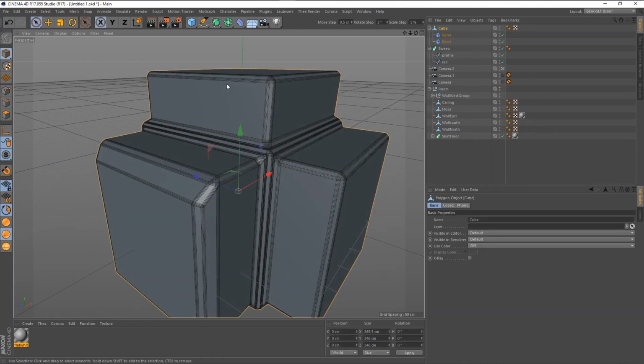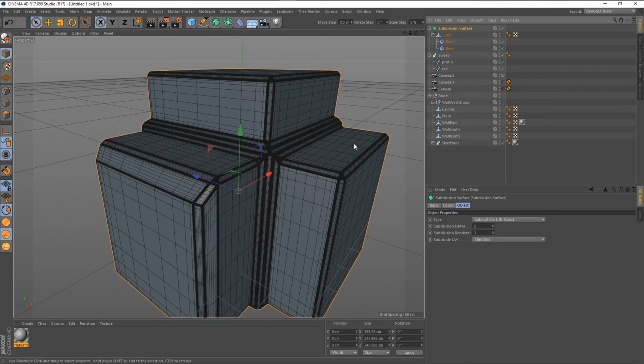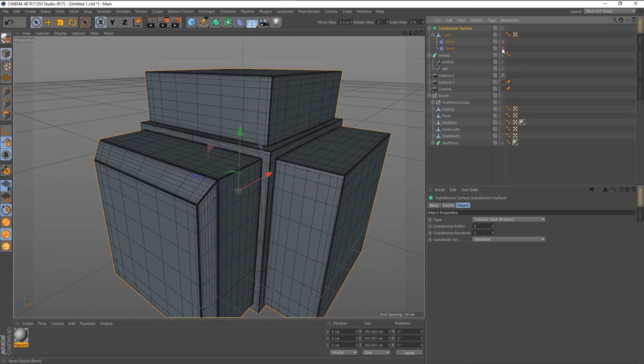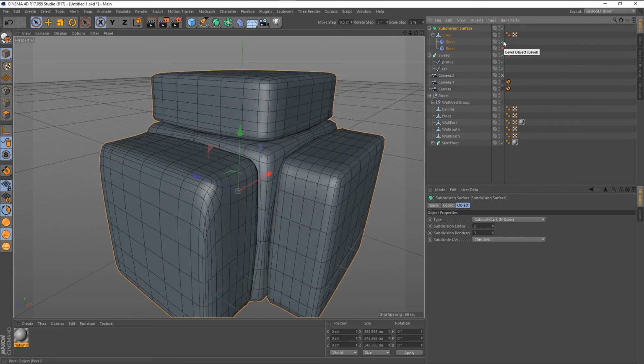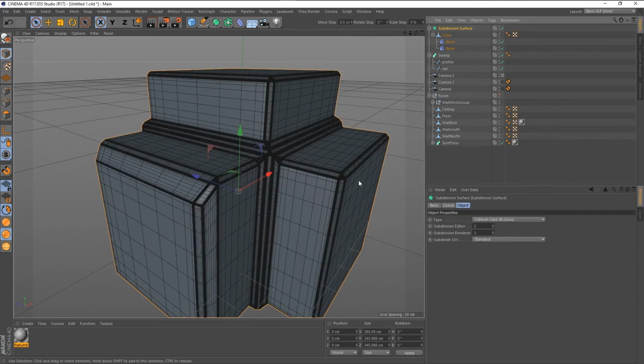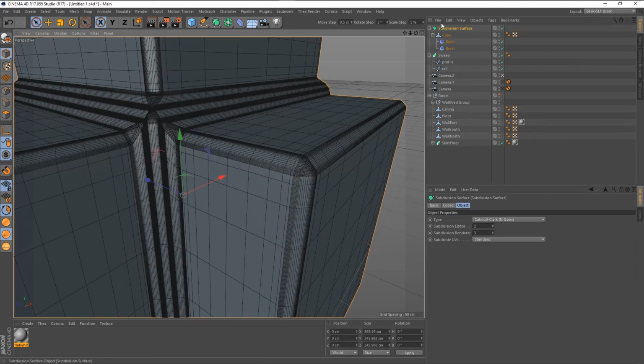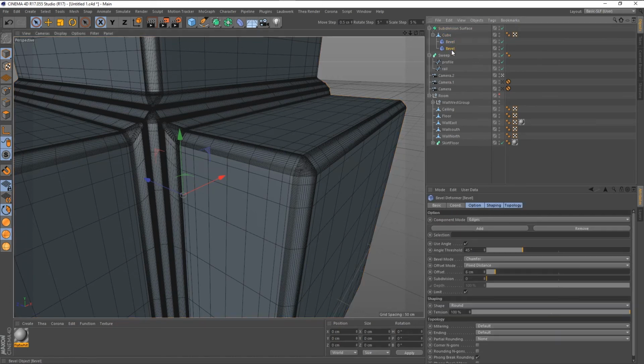And on top of this then, I can hold the Alt key down on my cube and hit subdivide right here like this, and it gives me my subdivision surface. I can disable those bevels, and you can see how they're affecting my subdivision surface. So those are stacked modifiers, but it's obviously weird because in Blender you would just see all three of these stacked one on top of the other, and so it's not clear which one is being initiated first, except that underneath the cube, this bevel is working first, and then it's this bevel.